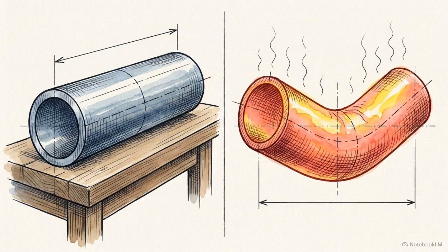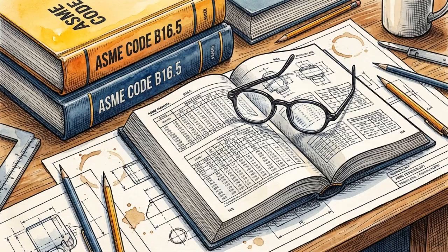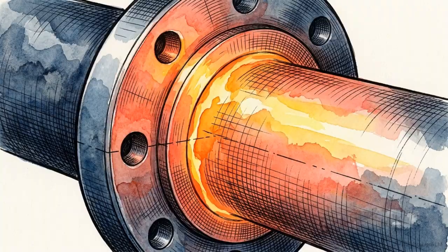The physics dictating this curve are straightforward. As heat rises, the yield strength of the metal falls. The flange physically weakens, forcing the allowable pressure to be derated. ASME has already executed the complex stress equations for every material group, generating these direct lookup tables. A class rating is a dynamic, pre-calculated curve that bends to the forces of thermodynamics.